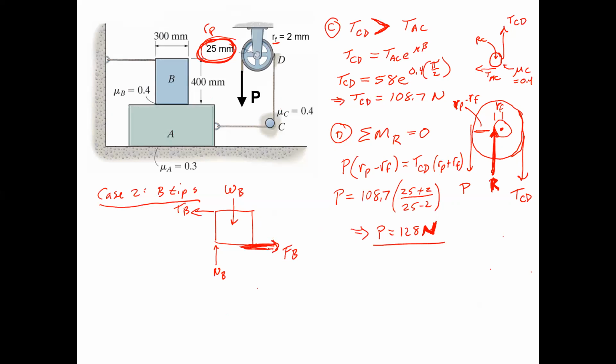Well, all we've got to do is figure out what is the force needed to get that thing. So we're going to basically find at what tension or friction force the moments equal 0 here, right? So point O, again, is this point on the left corner of the box where the normal force has shifted to. And the question is, is that going to stay on the box, or is it going to shift off? Or at what point are we at that corner? And then we figure out that's smaller than the force it takes to slide the whole thing.